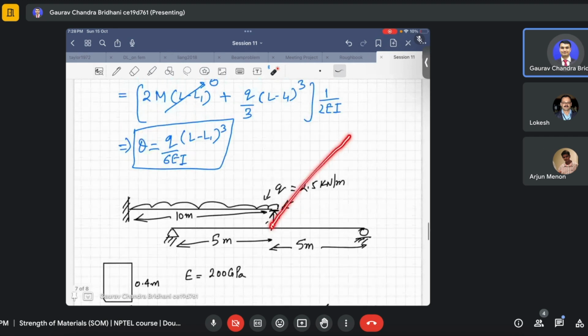So suppose this will go like this, so here it is fixed and it will be supported here as a roller, correct. So that load will get transferred. This is how you connect the beams, as I have told in some class or lecture back, because we have something called primary beam and secondary beam. So what happens, secondary beam comes and rests over primary beam.